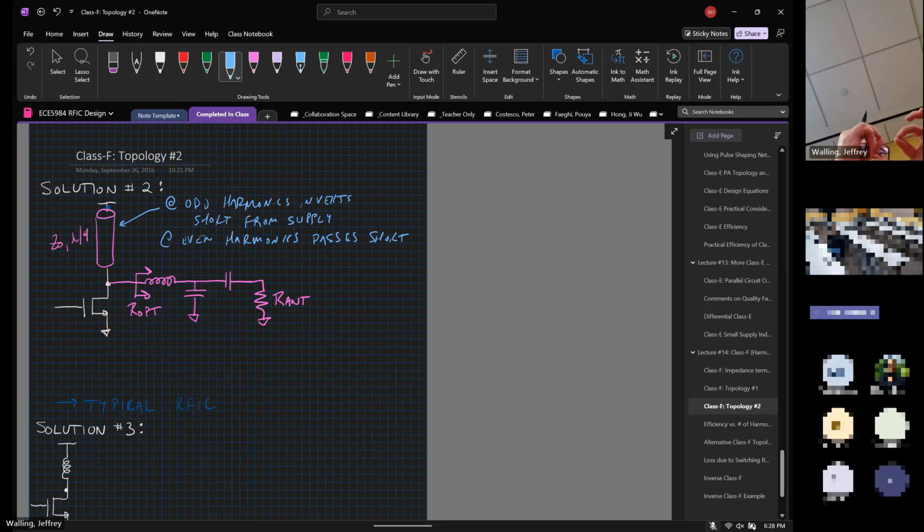They need the bond wires to be exactly aligned with one another because you're trying to keep the electric field and magnetic field exactly proportional to one another and propagating along the line without a mode transition or something weird like that. At low frequencies, it'll be okay, but at high frequencies, it will get kind of squirrely. Okay, so really, this is maybe a little bit better. We get the transmission line out of the series path, but it's still a big transmission line.